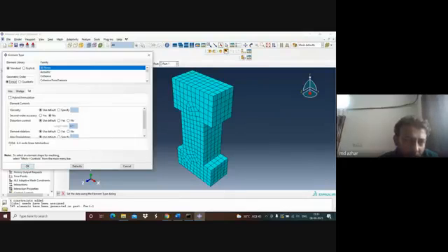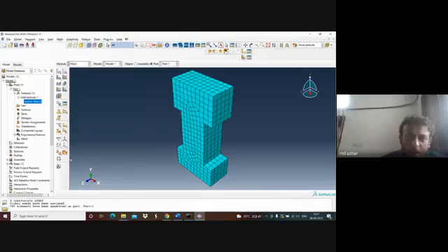You can see over here that you have the standard linear. You have selected here a 4-node linear tetrahedron. So that is a 4-node model. Similarly, if you look at the quadratic, that becomes a 10-node model. So let us just click on OK, and then it will be a 10-node model. So this is what we'll do. We will not select that.